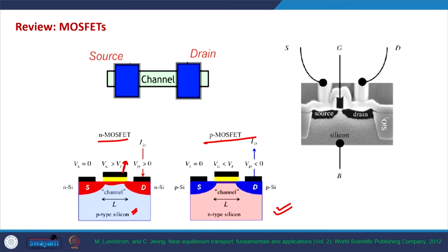So please keep this basic thing in mind. Similarly in a PMOS we need to apply a negative voltage, and the resulting electric field will create a P-type channel at the interface, and that will make a conducting pathway from the source to the drain via this channel, and this will be a P-type conducting pathway. Okay. So that's the basic thing about MOSFETs, and a MOSFET is a transistor essentially. That's what the T stands for, basically.